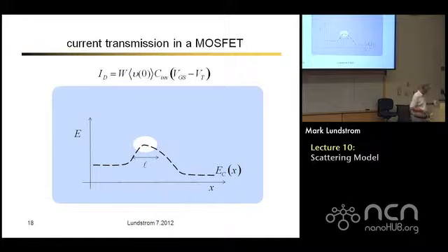So here's the picture we have. That white area there at the top of the barrier, that's the bottleneck. That's where the scattering matters. And what we've deduced is that the average velocity in that region is given by the smaller of the ballistic injection velocity, that's V sub t, the thermal velocity, or D over L. And what's D over L?